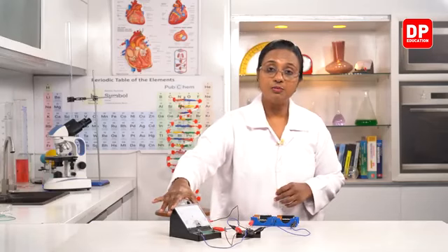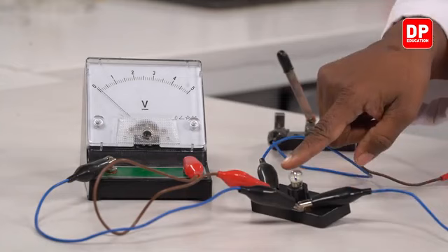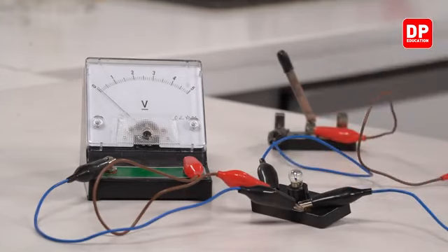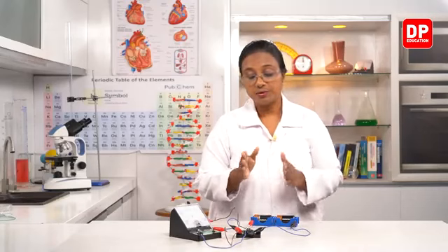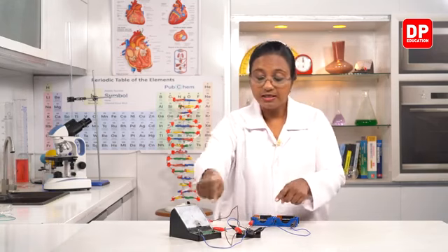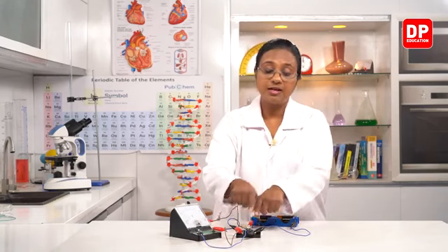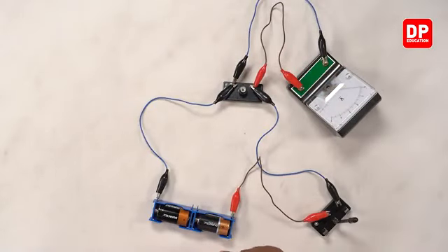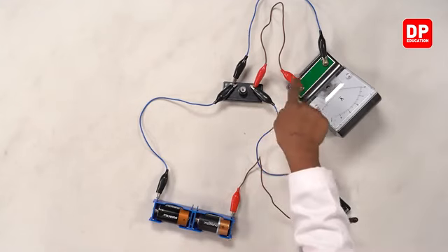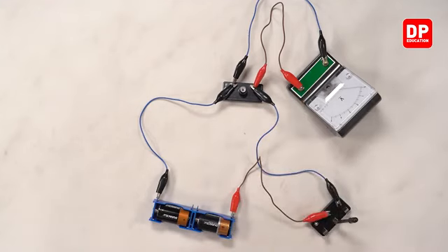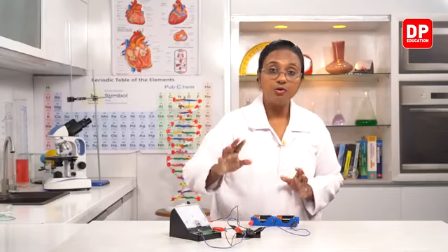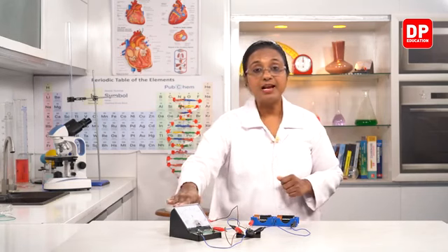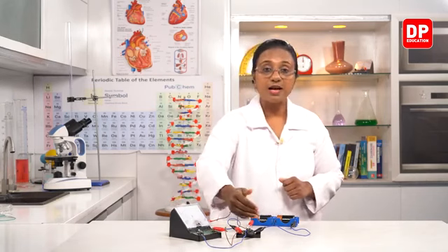Now look at the voltmeter. We need to measure the potential difference across the bulb only. So if you want to measure the potential difference across the bulb, the terminals of the voltmeter have to be connected here. Now here you can see this terminal is connected to the voltmeter, and this side also the terminal is connected to the voltmeter. Is that clear, students? So this is how you are supposed to connect. This is a parallel connection. Now this is parallel to the bulb and the dry cells.